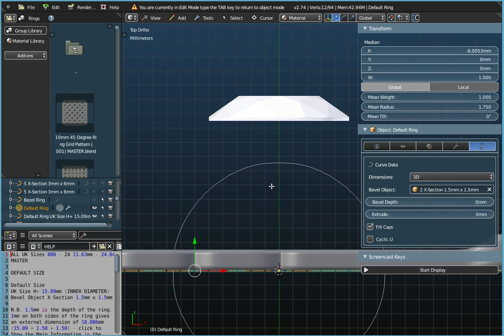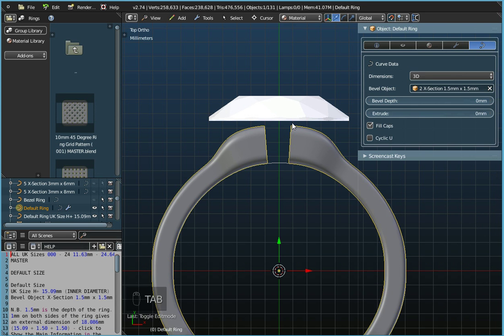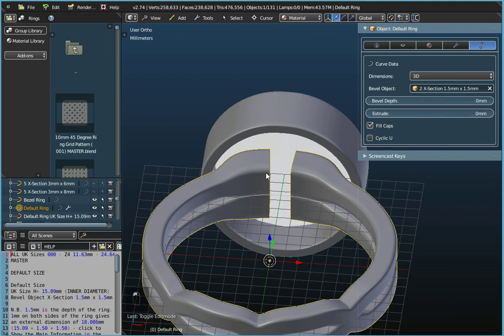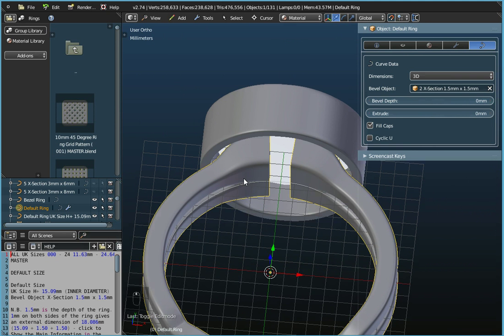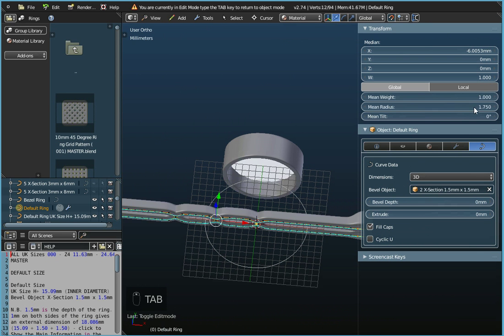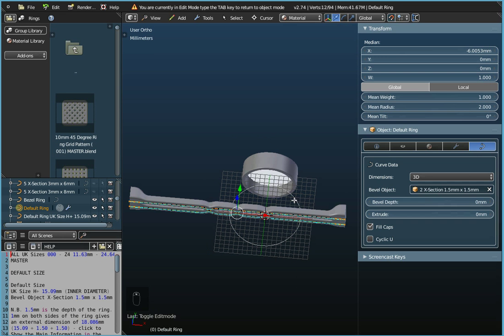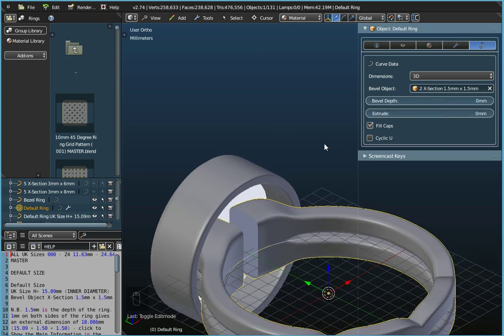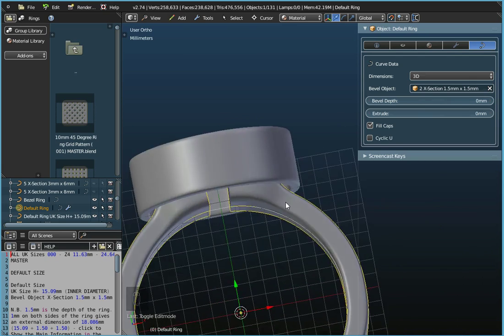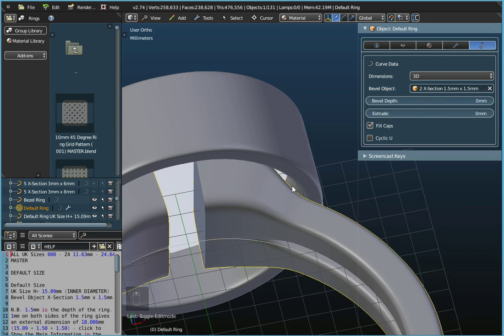And then if we go to view and top view, and if we press the tab key, I didn't switch on the screencast keys, did I? If I press the tab key to come out of edit mode, you see I've still got a bit of a gap there. And it's still not quite touching here. Okay, so let's tab key again. Let's try increasing the mean radius to 2 and tab key to come out of it. Okay, so we've got that now. We're still not touching here.